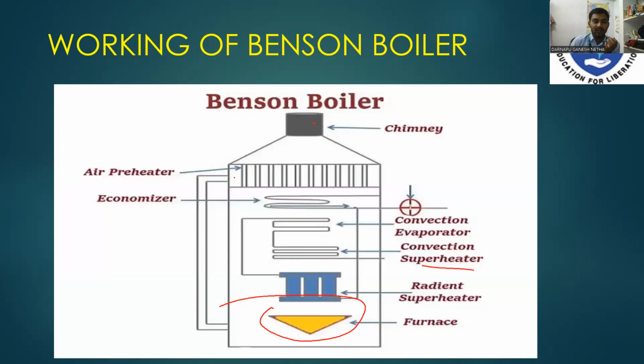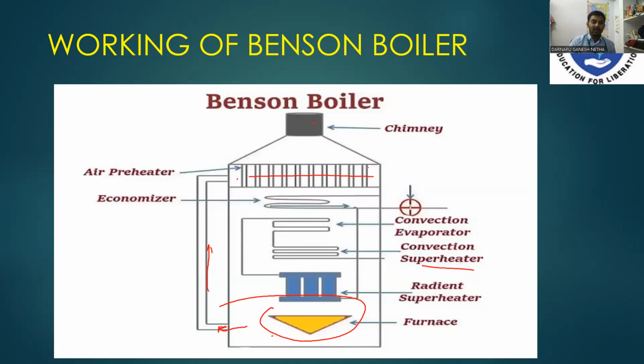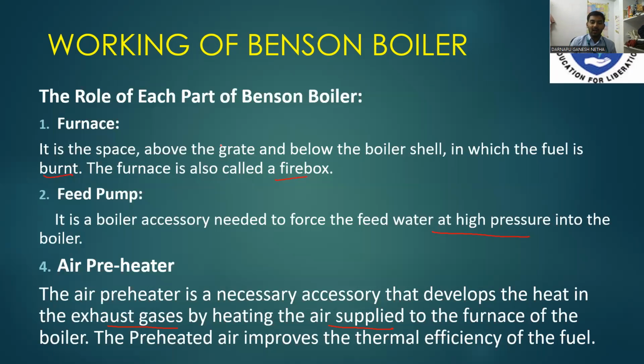Air preheater. This one. After the furnace, the air and gas will enter in this direction to the air preheater. This is an air preheater. So here the heat from the exhaust of the gas will be sent to the air preheater and supplied to the furnace boiler. This air preheater improves the thermal efficiency.